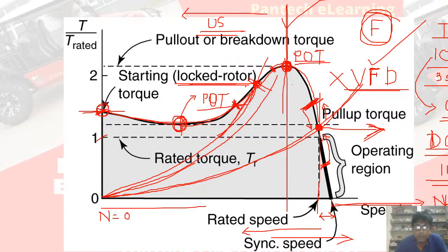It's well and good if I can control the transient within 1 to 5%, it can compensate. But if the electrical transient is higher than that, and suppose the variation is more and the operating point shifts more than 5 to 10%, then in both the cases my motor will stall, which is not advisable.